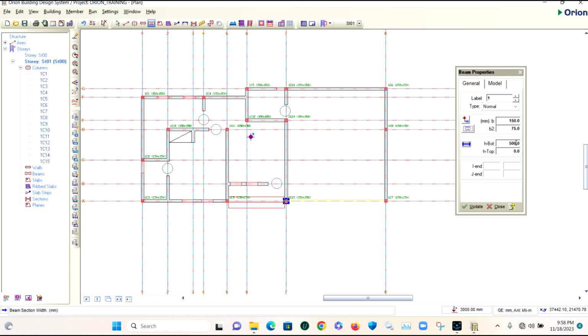So you check whatever the thickness of the beam you want to do is, then you insert it here. Once you get here, you can right click and it will show you different beam depths, then you choose from them. But you can also just type in the depth of your beam. Once you are done with this, you go back to insertion.